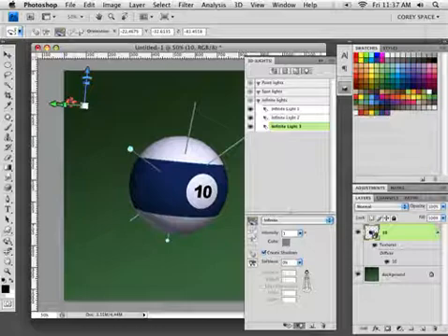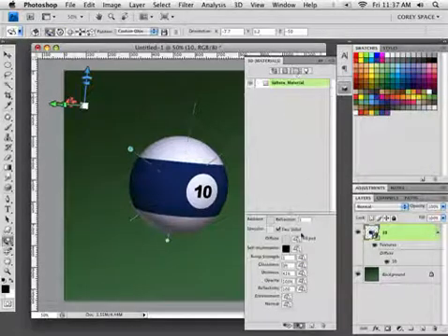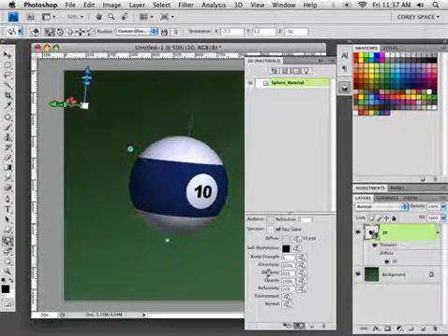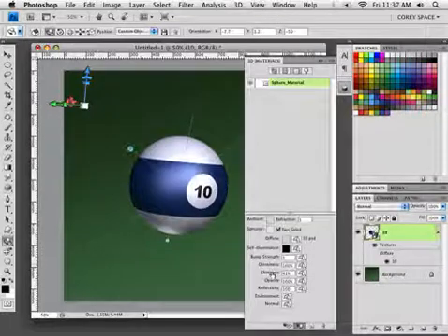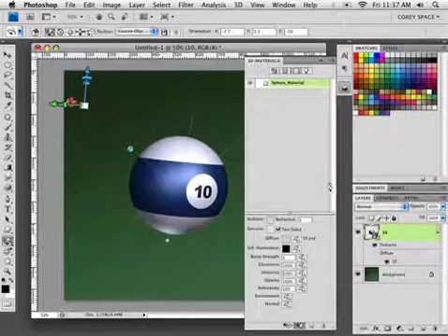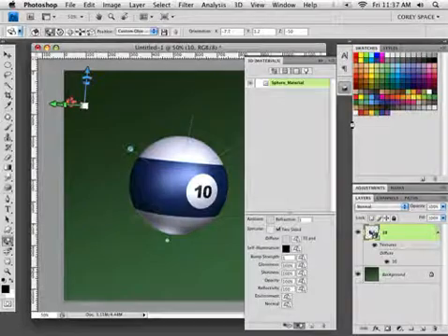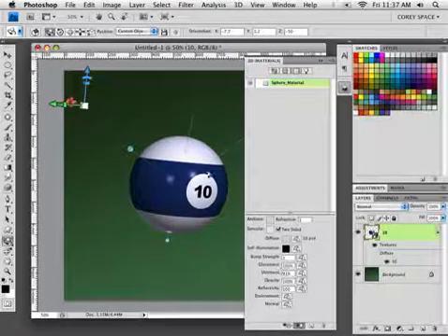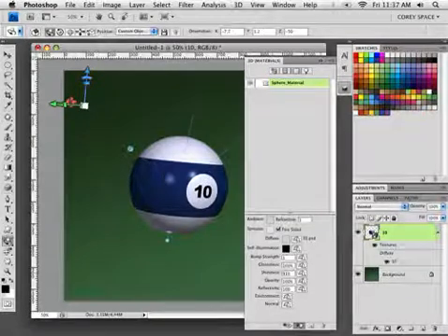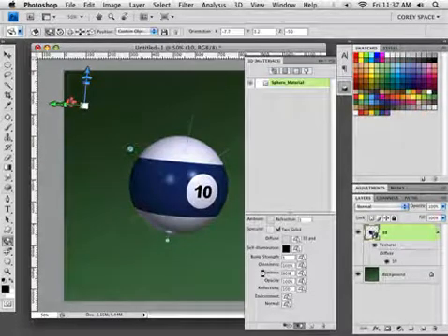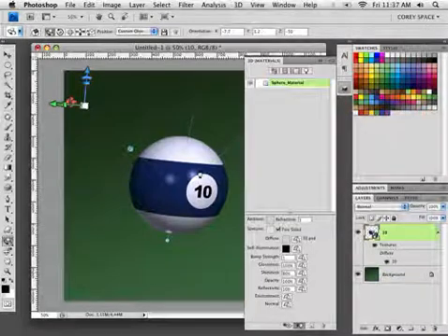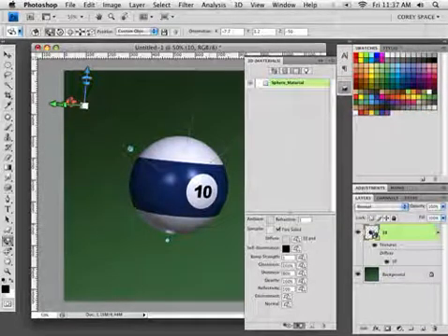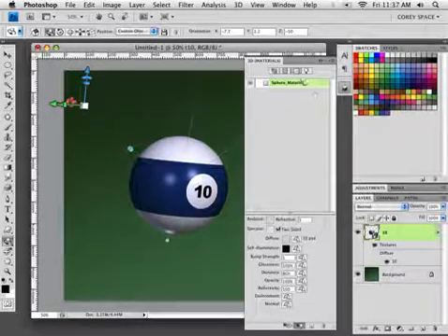I'm going to go over to here and click on the materials options over here, and we're going to increase the glossiness and the shininess because we know billiard balls to be really shiny, really glossy finishes on them. Take all that to 100%. You'll see, well, we can probably take that to around 90. It'll give me a flare out that glare a little bit. Well, let's make it about 80. So it looks pretty good. So we got the lights going on there.